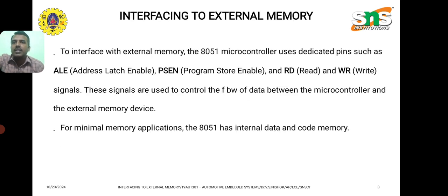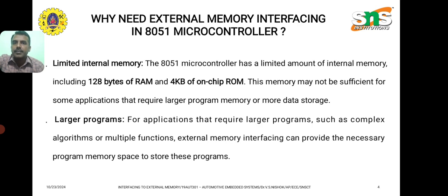Interfacing to external memory. To interface the external memory, the 8051 microcontroller uses dedicated pins such as ALE, address latch enable, PSEN, program store enable, RD read, and WR write signals. These signals are used to control the flow of data between the microcontroller and the external memory device. For minimal memory applications, 8051 has internal data and code memory.